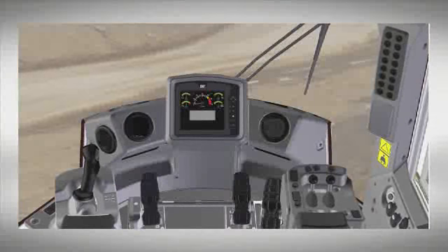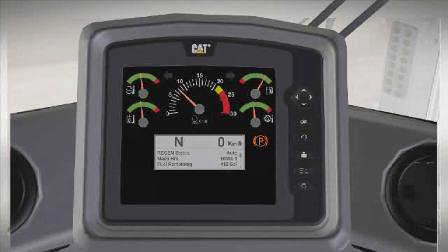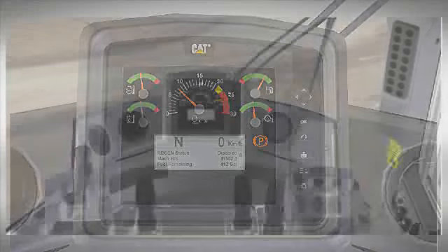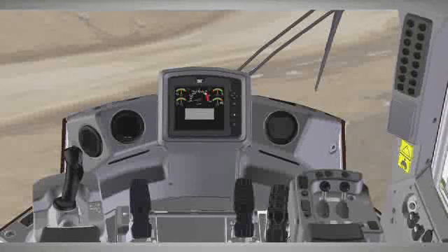In this section, we have 3 different regeneration scenarios using simulated automatic, manual, and disabled modes. All 3 are based on a wheel loader cab mock-up. We'll start by tracing the automatic regeneration sequence.